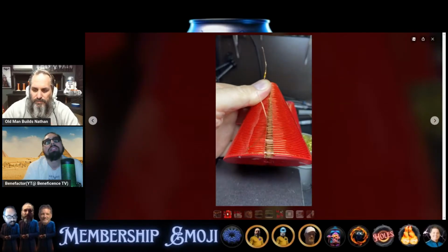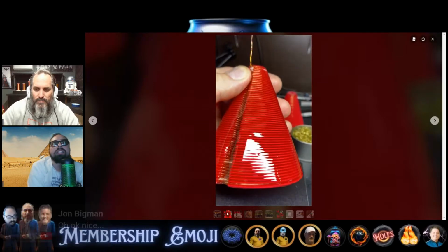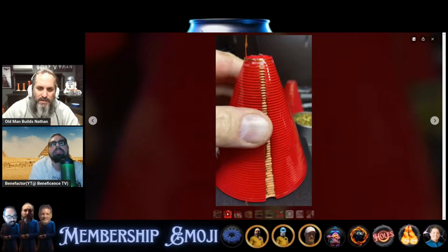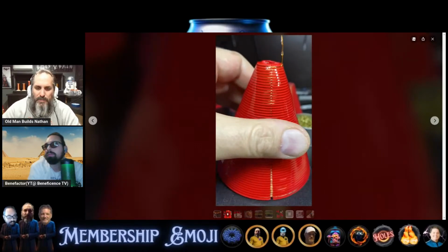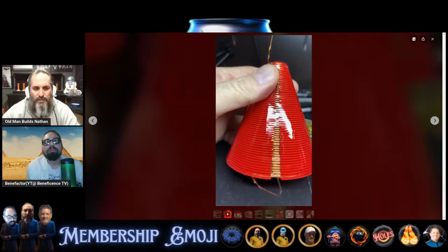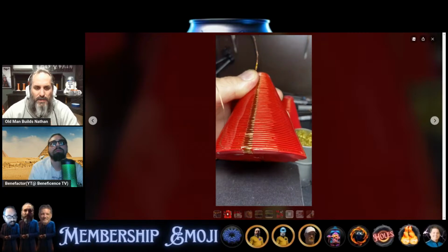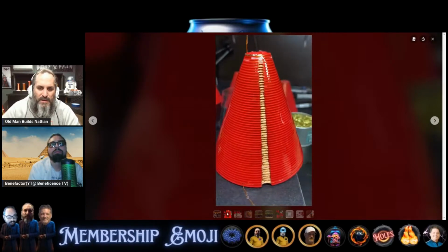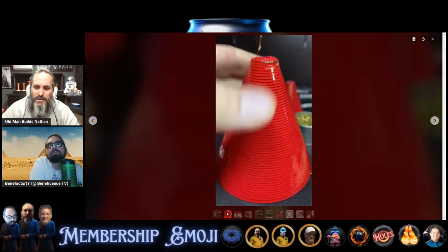Is that when you see kind of like that outbreak on the side? Well, it could be on the inside, everything, but if you've ever made an AC flyback, which is basically the winding he's putting on there, then the biggest part where they ruin each other is one wire next to the other. It'll melt the insulation on them and it'll fry. And it'll be in seconds, by the way. It won't be in minutes. It automatically does it. That's why finding a good AC flyback is important.